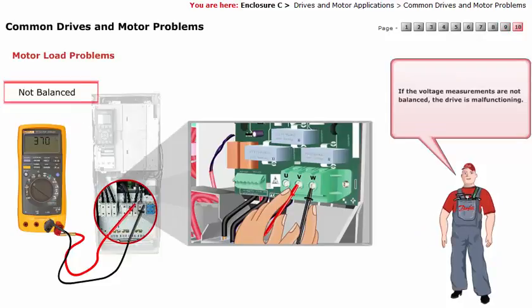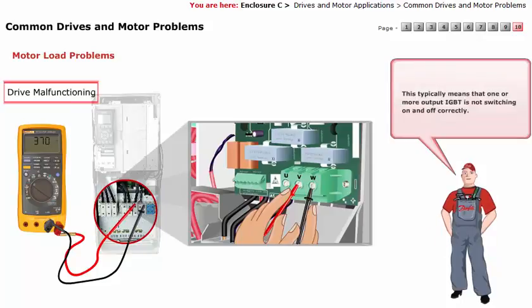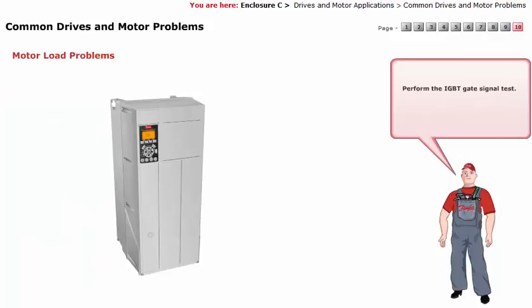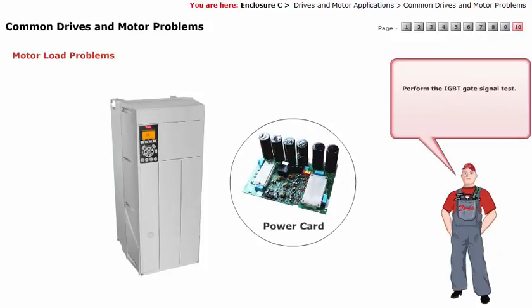If the voltage measurements are not balanced, the drive is malfunctioning. This typically means that one or more output IGBTs is not switching on and off correctly. Perform the IGBT gate signal test.